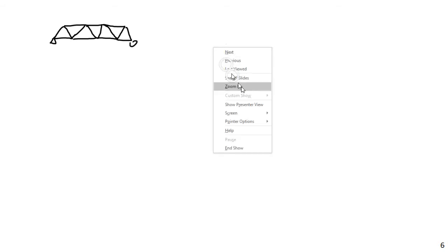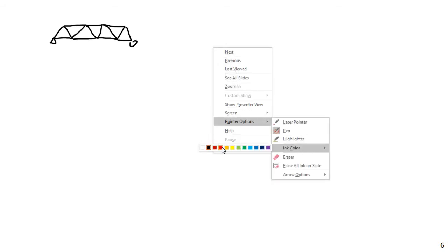There'll be tension members and compression members. Let's say it's a nice basic, simply supported truss, with a load at the middle. With a downward load, the top chord will be in compression and the bottom chord in tension.